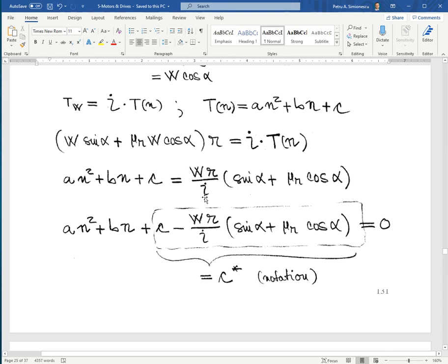So efficiency, the way I'm introducing it in the analysis, is by multiplying. I'm just making sure that I take that back. And sorry, I hope you're paying attention. So I'm dividing by efficiency. I'm making the resisting torque greater than for the ideal case by dividing with the efficiency to account for that.